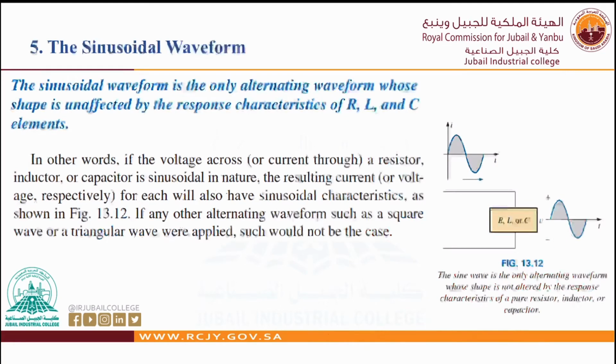Now, the sinusoidal waveform is the only alternating waveform whose shape is unaffected by the response characteristics of R, L, and C elements. So if I have a resistive load, the shape will not change. If I have an inductive load, the shape of the AC wave will not be affected.